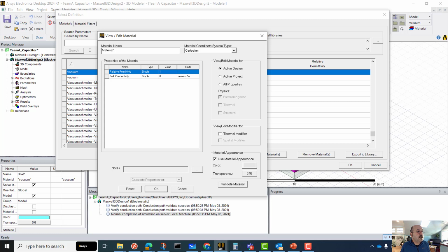Okay, there's no other material in this database. I get to assign a relative permittivity right now, and that's the actual thing I'm trying to do. Remember in class we did 3,000 was our solution. I'm going to see what happens when we go for something lower than that, 2,000. And it's not bulk conductivity, it's relative permittivity.